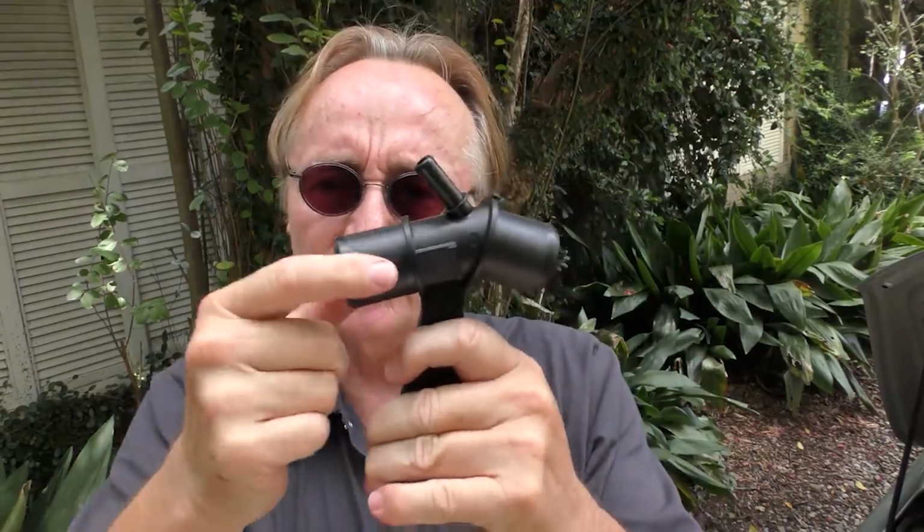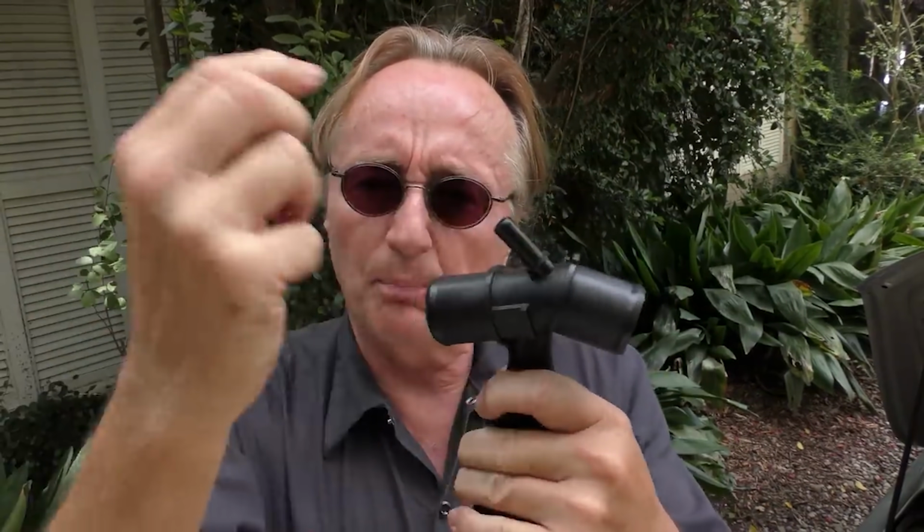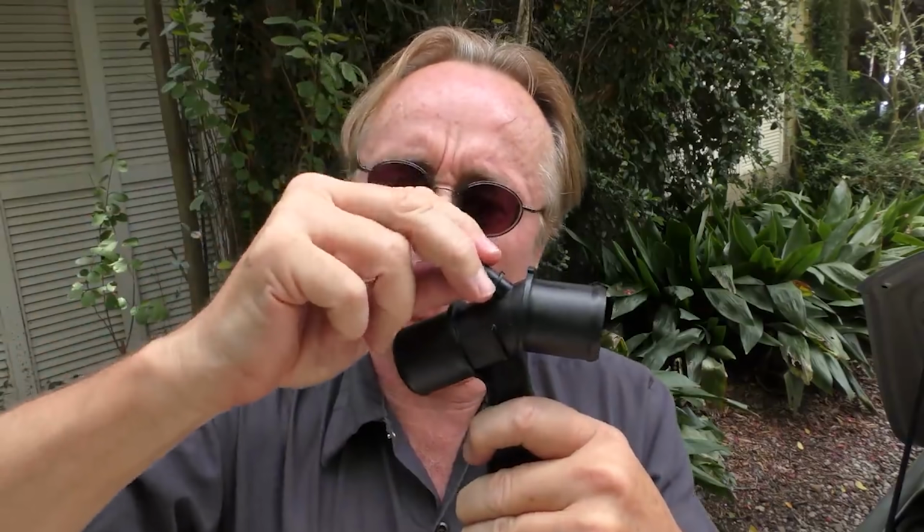Well, shame on Toyota in this case. They did like BMW. In 2010, they got the stupid plastic connector with the metal prong coming out that the little overflow hose goes into, and it broke off because it's cheap plastic crap. If they would have made it some other way like they used to and not have the junction here, it wouldn't have had a problem. Or if they would have made this out of metal instead of cheap plastic crap, it wouldn't leak. But they used cheap plastic crap, so we're going to change that first.